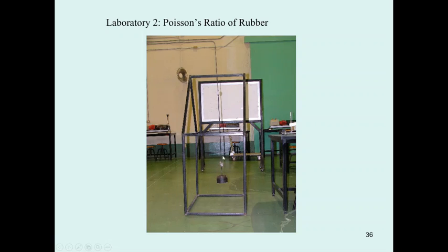How about the stress? Since you know the weight, and you also know the width and the thickness, you can determine the cross-sectional area of the rubber band. Usually, you measure one, two, and three times between the given lengths, and then you get the stress. So you can plot the stress-strain curve of the rubber band and determine its modulus of elasticity. Just beware the weight may drop to the floor, and beware of your feet. If the weight drops and hits your feet, that's going to hurt.